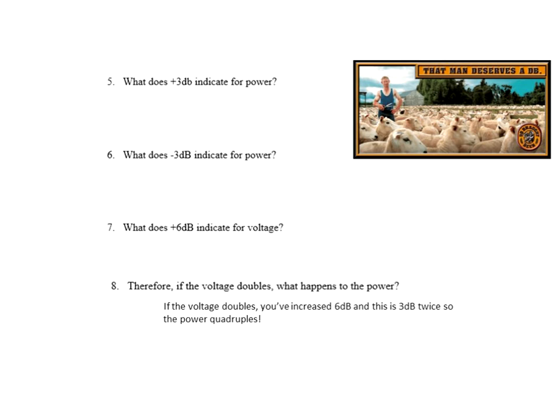Let's tell you why right now for number 5 on this activity sheet. A positive 3 decibels here for number 5 always means you're going to double the power. So if I was to start off with 1 watt and I had a positive 3 decibel increase, that means I would have 2 watts. Or if I had 2 watts and I had a positive 3 dB increase, that means it would be 4 watts. So anytime you have the number 3, that means that you're going to have a doubling of the power.